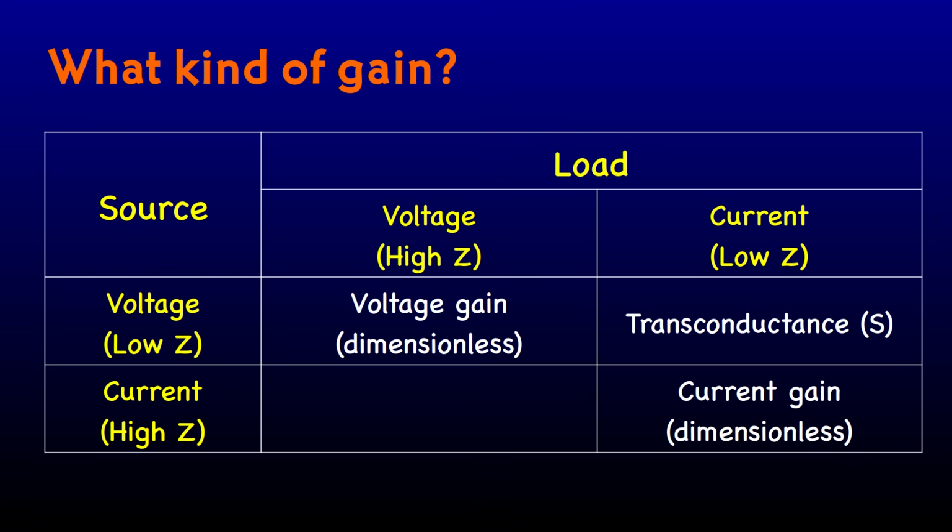Sometimes we want to have a circuit whose output current is proportional to the input voltage. Maybe we need specifically to regulate a current in the outside world, perhaps in an electroplating tank, or in the drive circuit for a laser diode. The performance figure for a circuit like this is the change in output current divided by the change in input voltage.